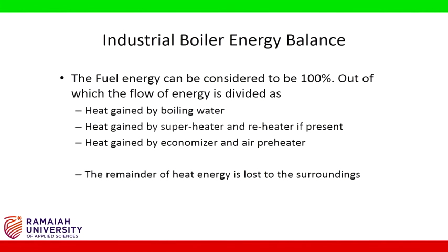The fuel energy can be considered to be 100%, out of which the flow of energy is divided as heat gained by boiling water, heat gained by superheater and reheater if present, heat gained by economizer and air preheater. The remainder of heat energy is lost to the surroundings.